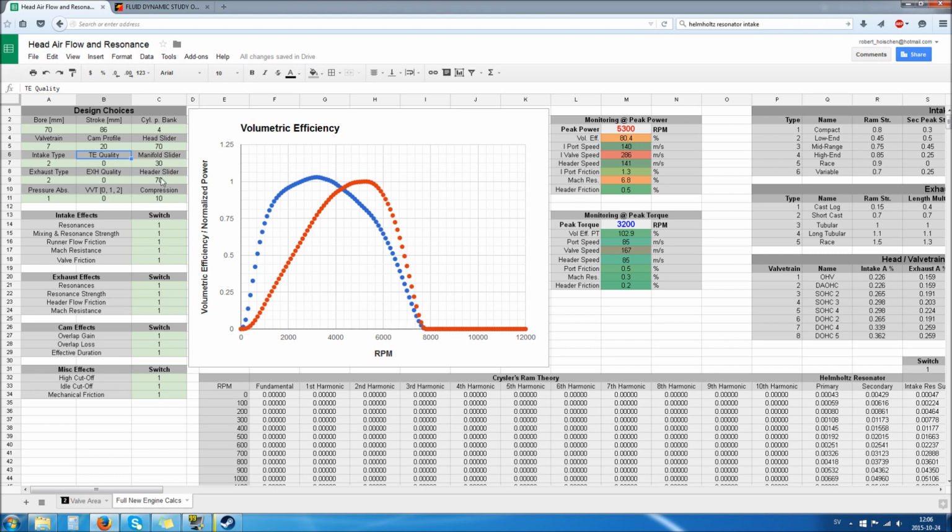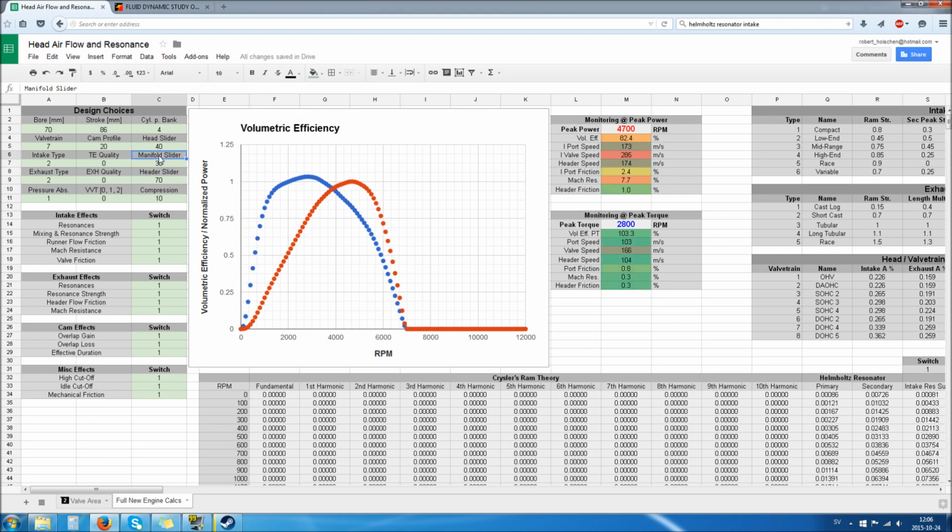Alright, so we have moved down the whole thing a bit. And now, let's see what we can do. We want to probably open up this a bit less. So, yeah, that's looking much better. So now we have optimized the flow for lower speeds, and we are getting to 1 volumetric efficiency at 2000, which is pretty tough because these engine sizes are not really made for good resonances down low, and you have to be a bit tricky to actually get it down there.